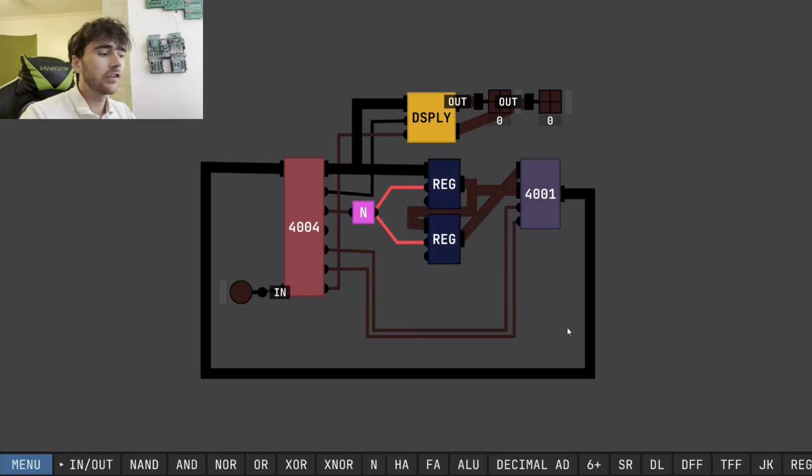And it's 46 instructions, and as you can see, it's really oriented towards being a calculator. It's really good at being a basic calculator. But that's essentially all it was made for, and it can do a few other things too. But again, the instructions were about 8 to 9. The first 3 were the addresses of the ROM, and then we have the decode, and then the next 4 was the execution part of the thing. So that's essentially how the 4004 worked.